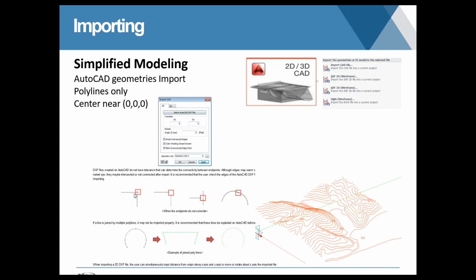So these little details have to be cleaned up, and you want to make sure, ideally before you import, although you can also correct this once the geometry is in place. Sometimes there's an overlapped line, a line in the same spot, like two lines that visually only look like one. That would throw off, not the import, but maybe once you try to mesh, you might get some sort of duplicate geometry. So we also have tools to clean this up within the program, but these are general recommendations before you import.